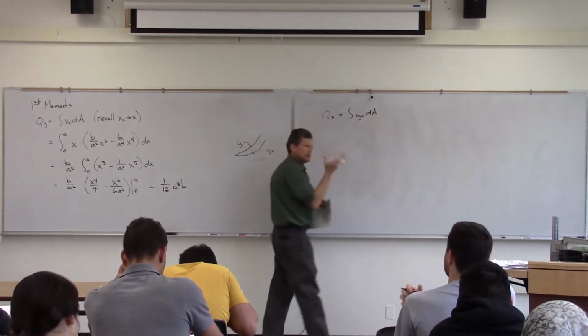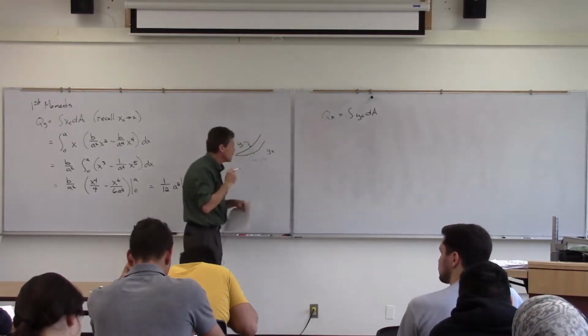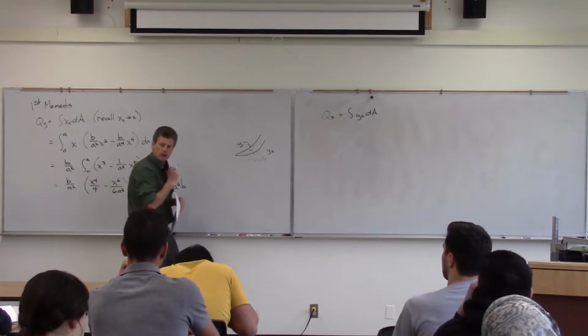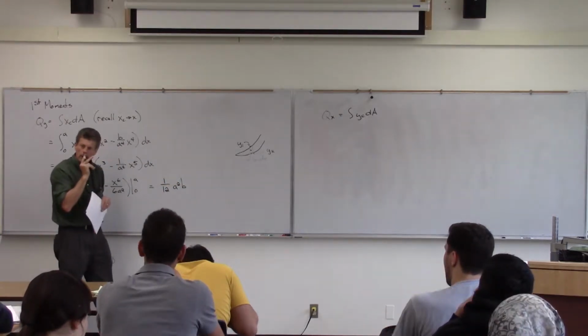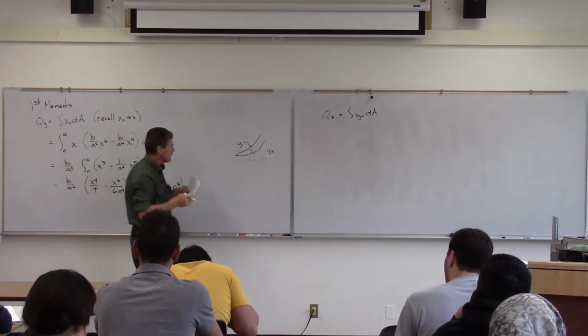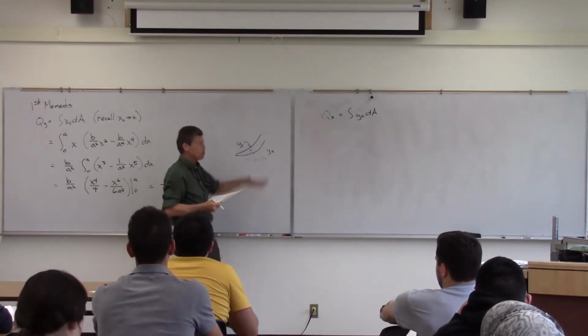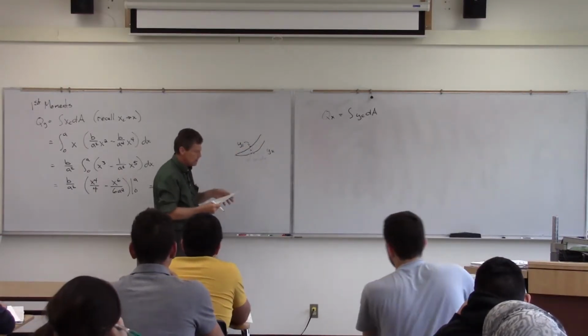Okay, the slightly trickier one now is going to be this YC. And again, the situation here is what I want to do is find the center of that rectangle. Now I can't go 1/2 of y1 anymore because my bottom is now coming up with me too there.